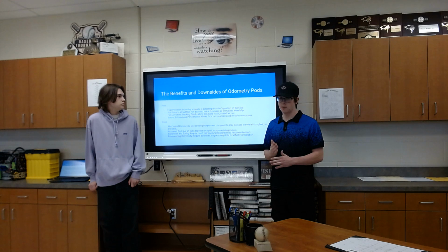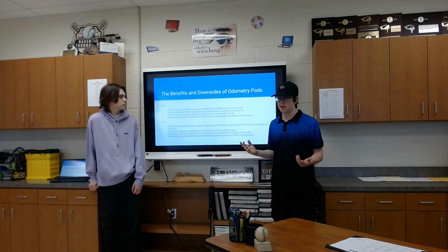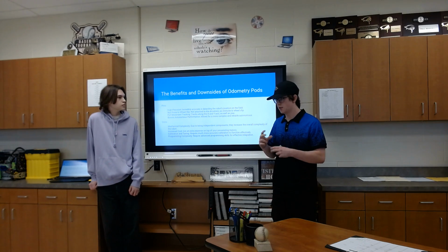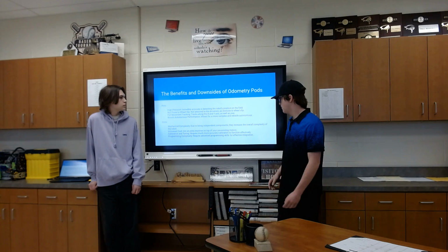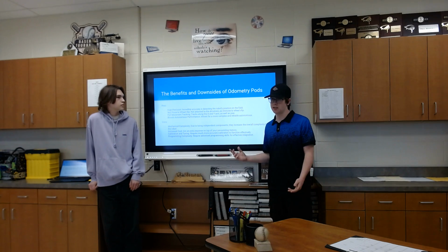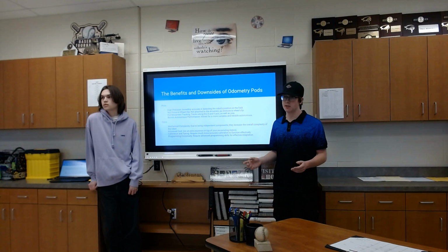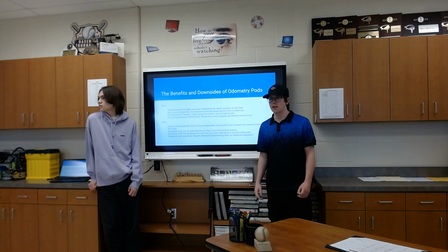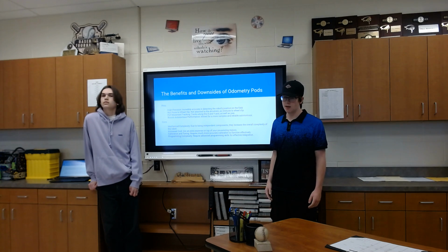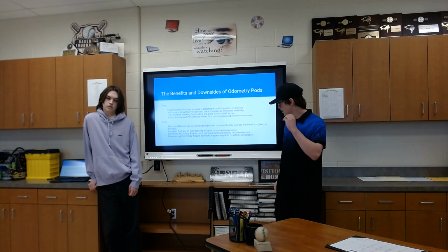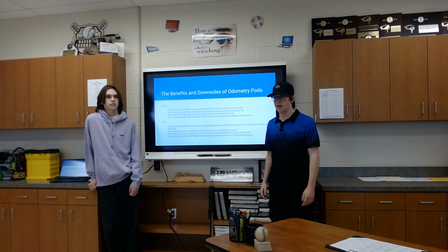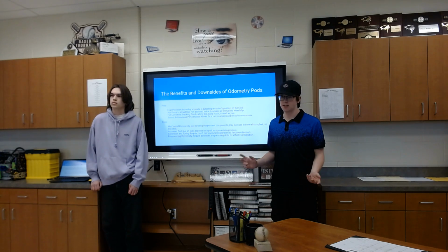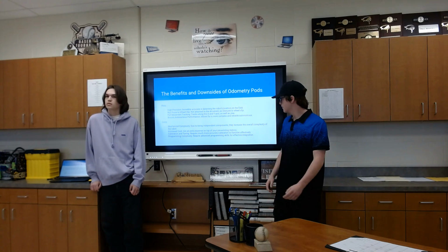They're individual components, so they make your robot have a much more complex assembly. There's an increased cost as they're not integrated in your pre-existing motors, so you have to buy a new component. They require much more accurate calibration and tuning to work effectively. And there's more programming complexity as it has its own programming.